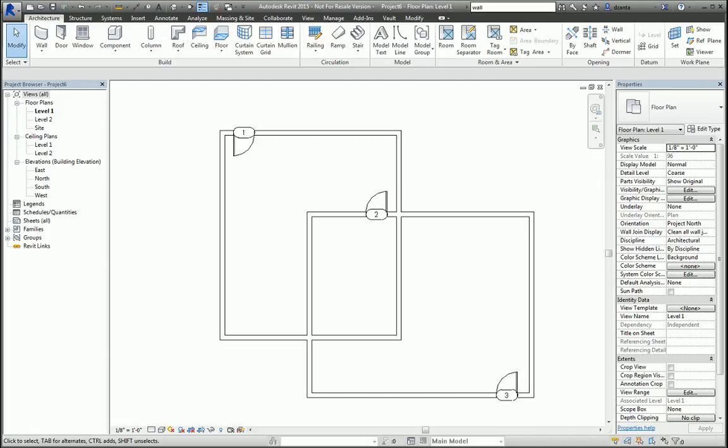In today's screencast, we'll be looking at the actual Revit Component command. Here I am in a Revit project. If I look at the Architecture tab of the ribbon, Build panel, I have the Component command. If I hit the little black arrow next to it, I can get a menu drop-down where I can either place a component or model one in place.